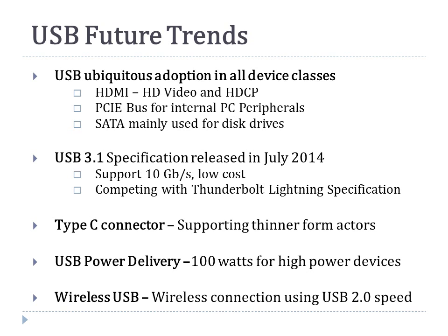USB is also coming up with a new type of connector. We discussed type A and type B connectors. It's coming up with a type C connector, which supports the emerging devices which have much thinner form factors. The USB type C connector can be plugged in any way. Currently USB can only go in one particular orientation because of the placement of the USB 3 and USB 2 ports, but the type C connector can be connected in any orientation. And as I discussed before, the new power delivery spec is coming, which can supply 100 watts of power for high power peripherals, and this will be very useful where we do not need so many power supplies for all the peripherals, as they could be powered using the USB bus.